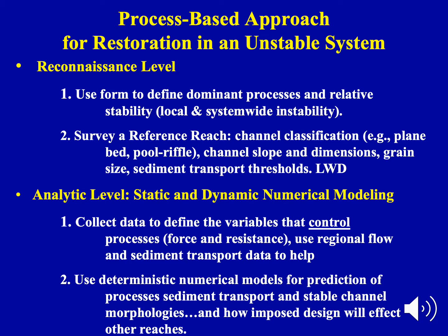I like to look at it as first starting with a reconnaissance level, going out into the field, finding your reference reach, finding out what is working, what are the forcing mechanisms that are naturally occurring, and essentially trying to replicate that reference reach. Rather than going into a certain channel predetermined that you're going to make boulder weirs or root wads, if that's not what's actively working in the system, don't necessarily try to replicate it.